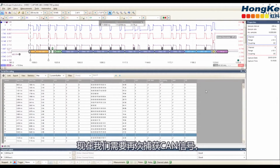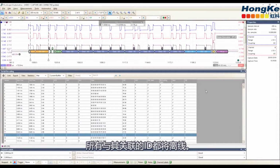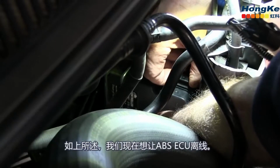Right, so now we need to capture CAN data again, but this time we're going to do the same capture and decode, but with the ABS ECU disconnected. So the ABS ECU and all its associated IDs will then be offline. So as we mentioned, we now want to take the ABS ECU offline.